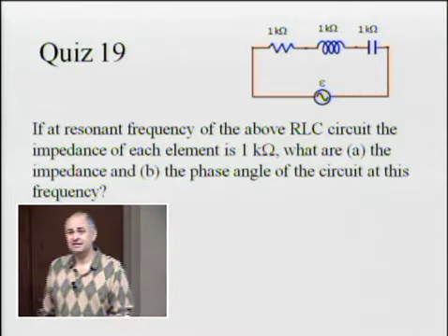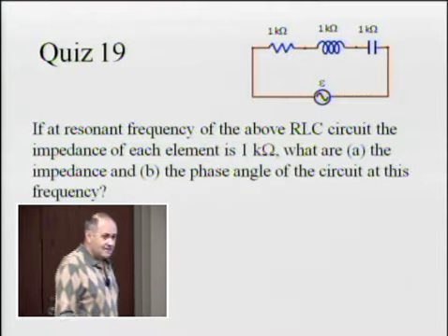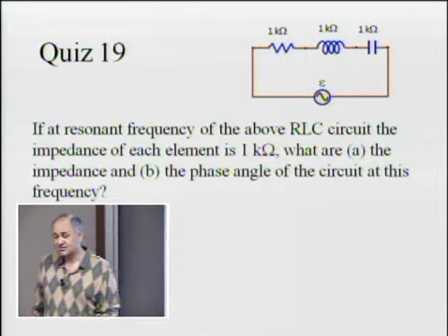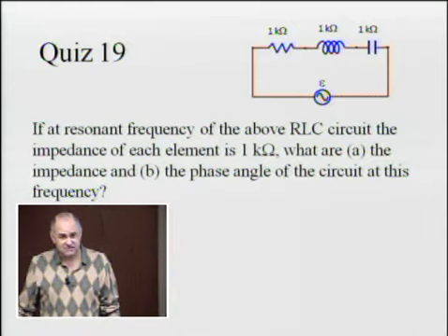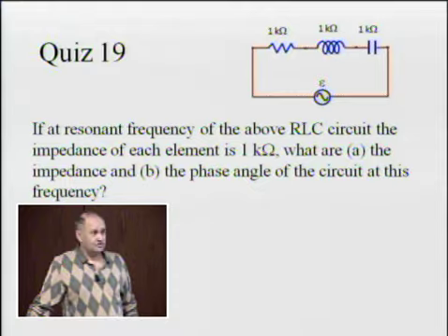And if these two impedances are equal, when we combine them, they will add up to a zero impedance. Impedance of inductor and capacitor connected in series, if the impedances are equal, adds up to zero. And the reason for it is that the phases are opposite. So remember that when we combine impedances, we don't just add them like resistances. We have separate rules for these.